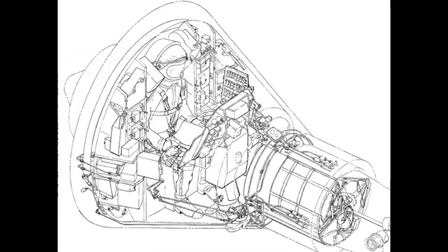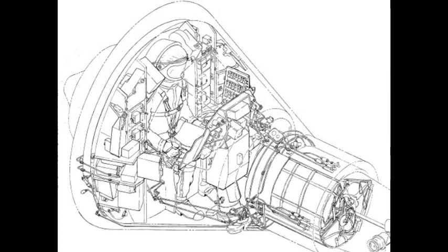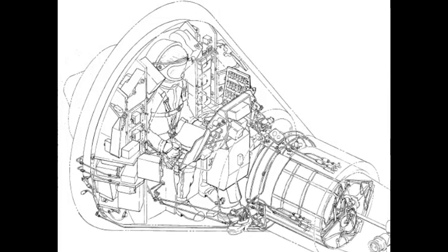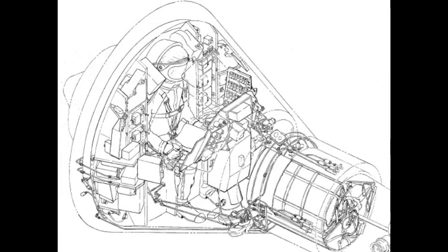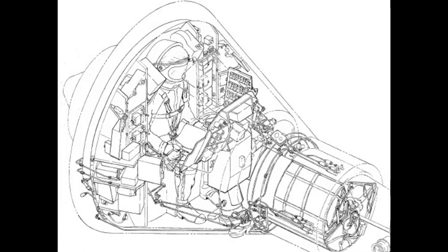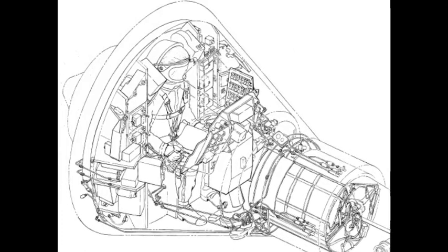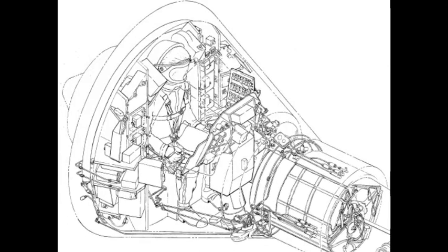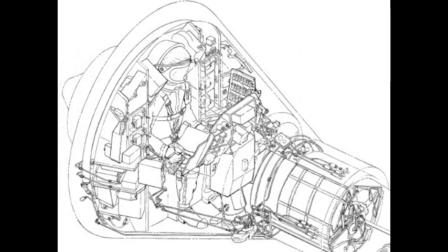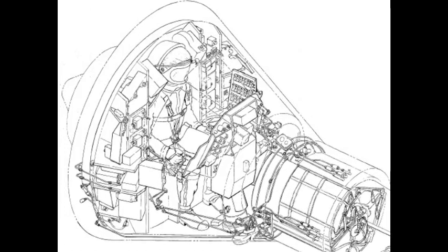220. The exterior of the clamp ring is covered with a heat shield that protects the explosive bolts from excessive heating. Thermoflex insulation is provided on the clamp ring shield interior. The heat shield is attached to the clamp ring with screws. 6 cable straps are bolted to the clamp ring heat shield and to the missile adapter. These straps aid in capsule adapter separation by retaining the clamp ring to the adapter when the explosive bolts are fired.